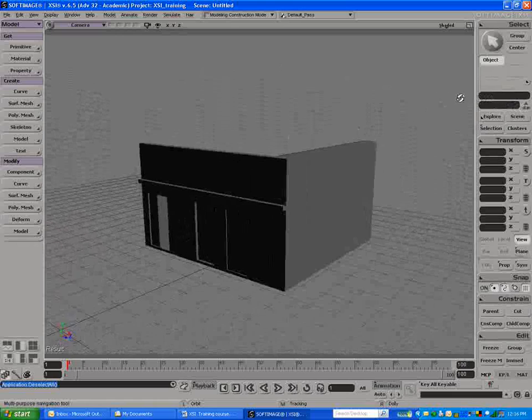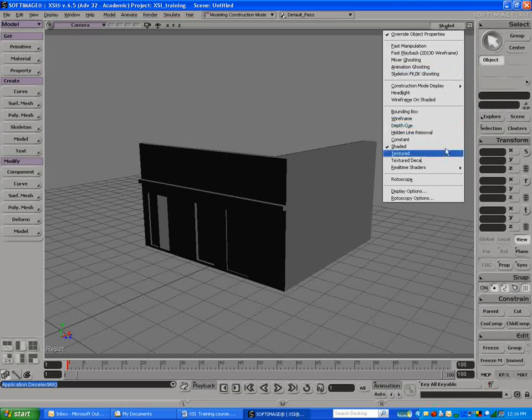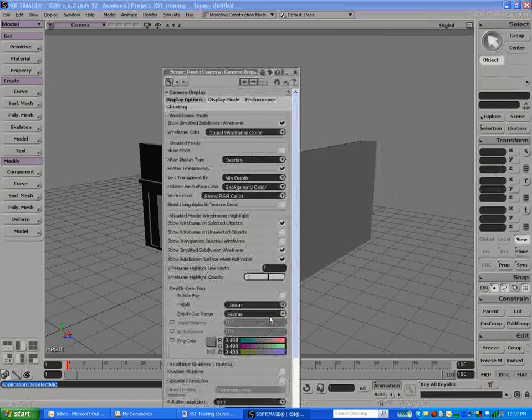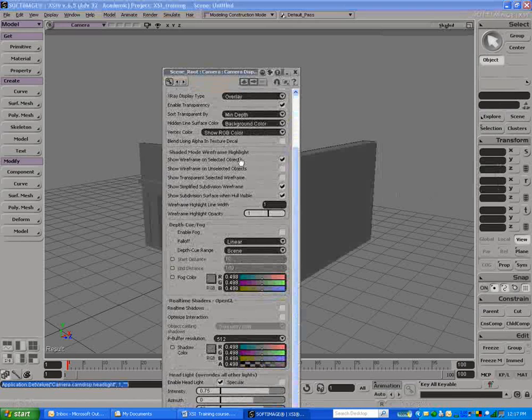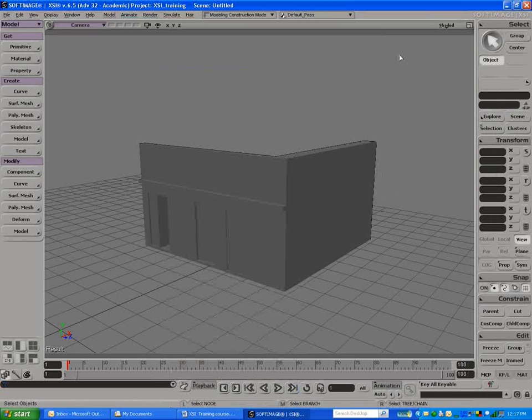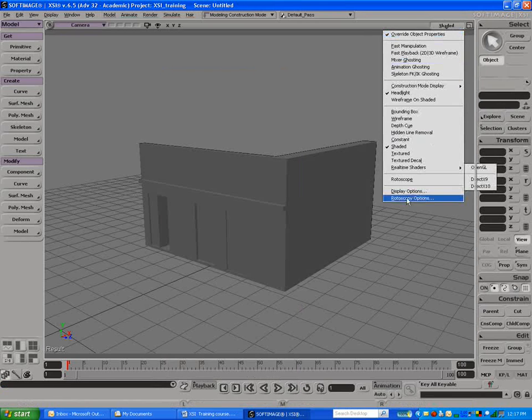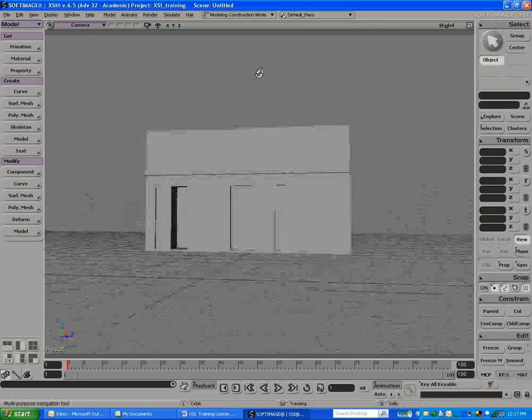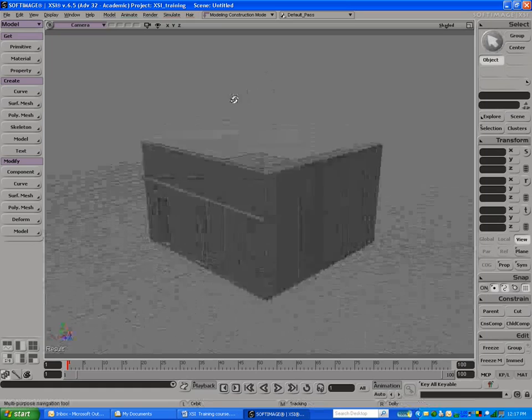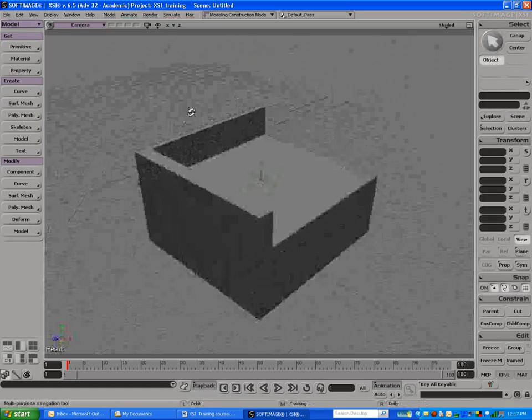We can, if we want to, go in here and just go to display options and add a headlight. Just check the lighting is okay. Now you can add specular as well to that, and that's just under the display options per window. And now we can see, as we spin around, how everything looks, especially now with the headlight.